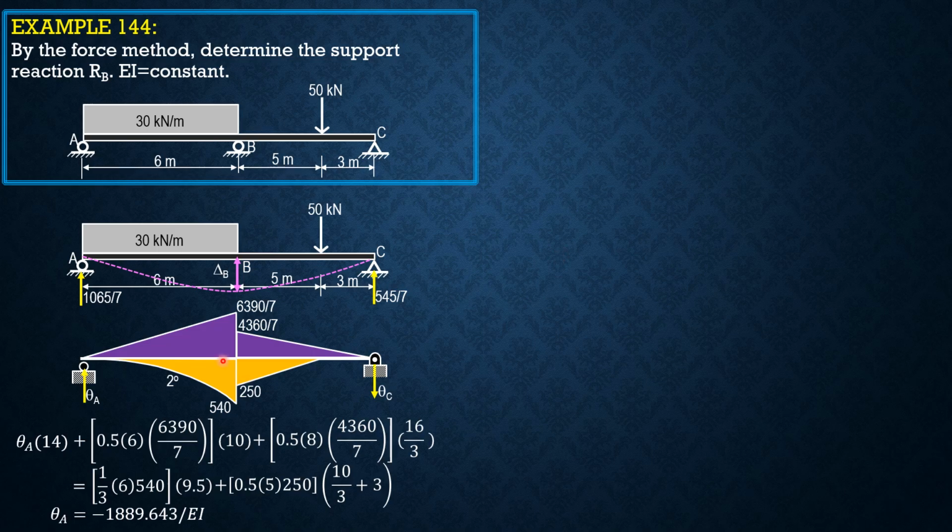Having found theta A, we can now solve delta B. So that's theta B positive, delta B counterclockwise positive. So summation moment about B considering AB. So delta B plus moment of this area, which is 1/3 of 6 times 540 times 1.5, or 6 over 4, equals theta A, which is negative 1889.643 over EI times 6.